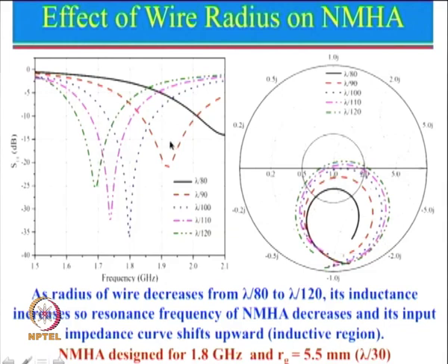After that, you have a choice. One choice will be that you increase the ground plane size even more, so that the curve will shift up, which will reduce the frequency. Or we can increase the length of the wire slightly, which will reduce the frequency more. So by doing these kinds of things, we can do a proper optimization. We can get a good impedance matching also. So by combining all these things, finally we optimize the antenna.